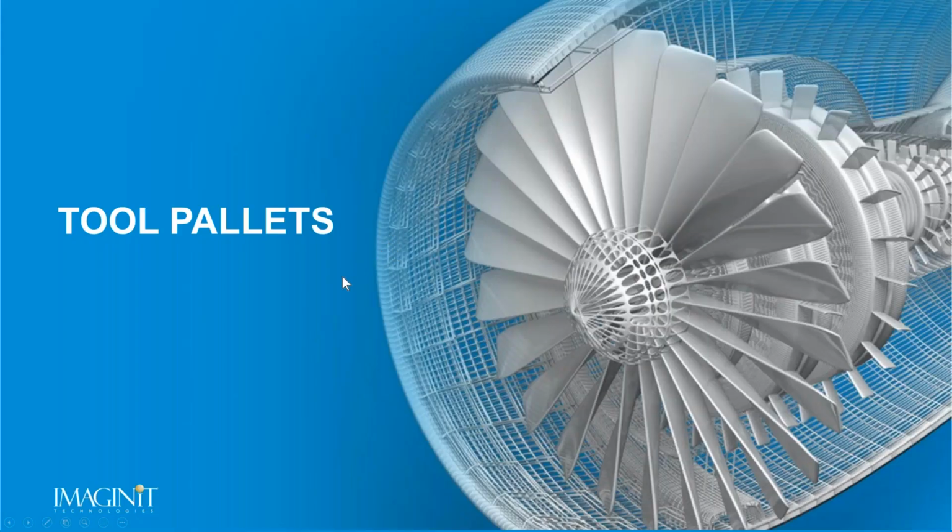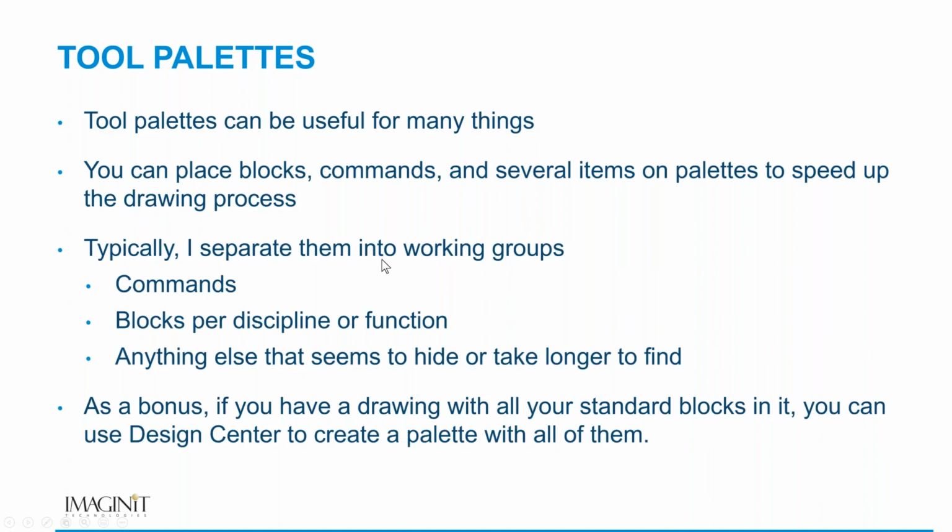Now we're going to talk about tool palettes. How many of you actually use tool palettes today? And if you're not using them, that's fine. I just want to show you that tool palettes can be useful for a great many things. You can place blocks, commands, several items, and other things onto palettes to speed up the drawing process.